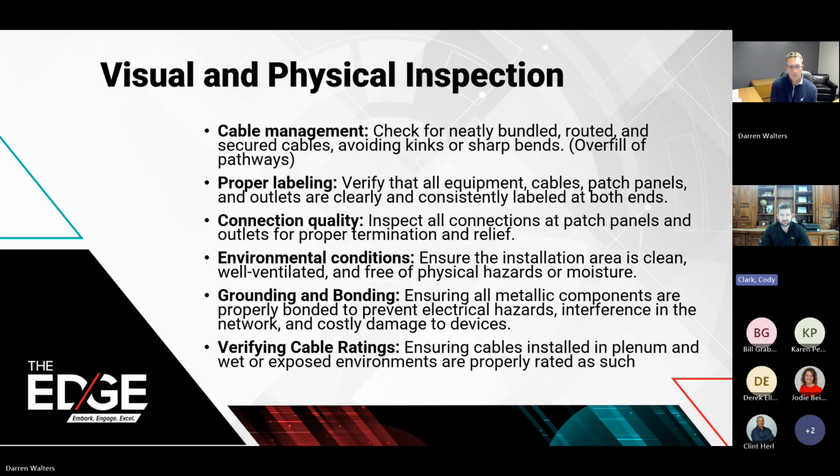One thing you see often is overfilling of pathways. That causes a lot of issues, including increased heat whenever you have too many PoE cables running through an area, and then just being able to service it without causing damage or accidental disconnections. Proper labeling also helps when you're tracking down your patch cords, making sure that you're not unplugging or plugging something into the wrong connection.